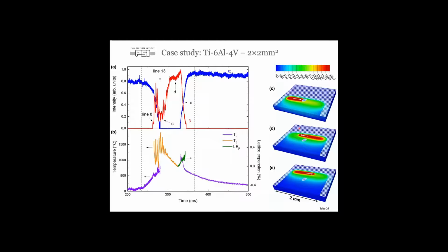And so we see here also on this schematic that at this point number 4, the laser is already several tracks away from our probed area, but the temperature remains high enough because of the short scan vector length to keep this beta phase for an extended period. And once the laser beam is really far away, the temperature, as you can see here, is slowly cooling down with typical rates of about a few 10,000 Kelvin per second. When the temperature is low enough, we create the alpha phase again and our beta phase is disappearing.